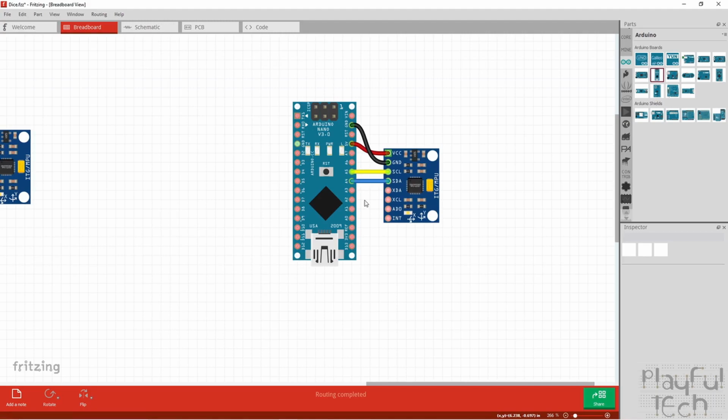Okay, great. Now if you're really paying attention, you might think, well, hang on a minute, that's still not right though, because when the Arduino is not writing to them, they must be pulled up to a known state. And if this is a 5 volt Arduino, surely the known state is going to be 5 volts. And you'd be right there as well.